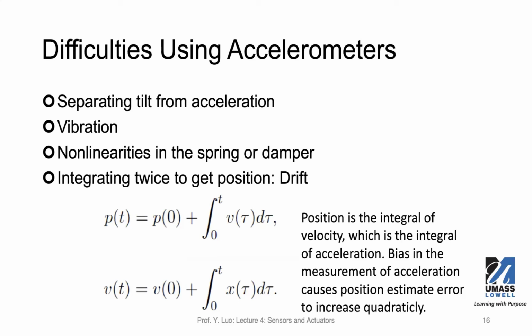As we saw earlier, gravitational force can be applied if you have the platform tilted to certain degrees. Also, vibration will cause the accelerometers to have a lot of interference in finding out the displacement of the moving piece. The x could be impacted by the vibration.